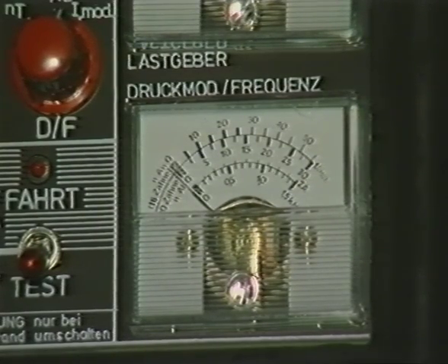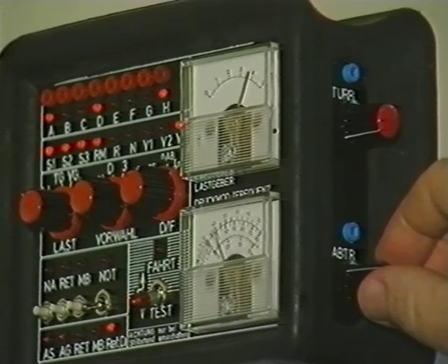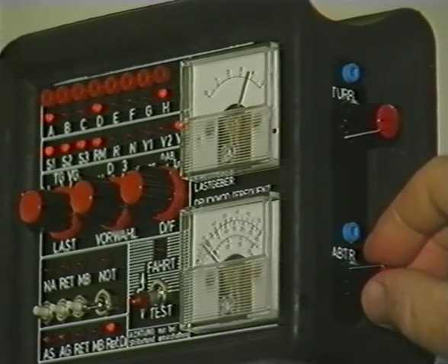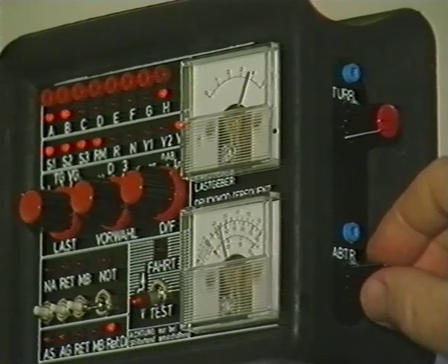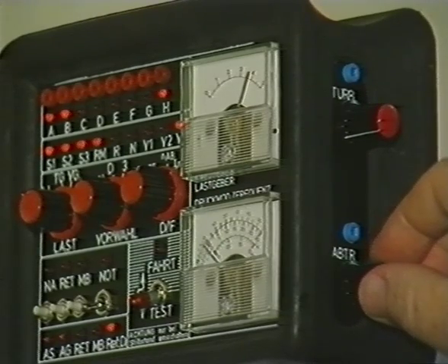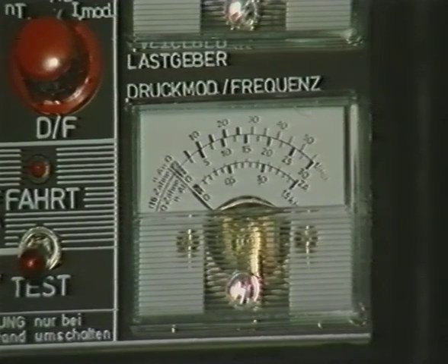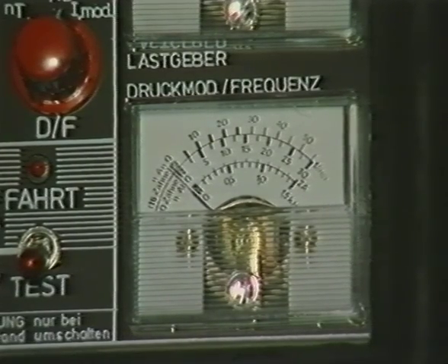It should be noted that if there is no reading, this does not necessarily mean that the control panel is at fault, because if the throttle modulator circuit is broken due to a fault in the solenoid or harness wiring, no current will be drawn. Therefore, it'll be necessary to conduct a resistance check on the throttle modulator solenoid and continuity tests on the harness before reaching a final conclusion.